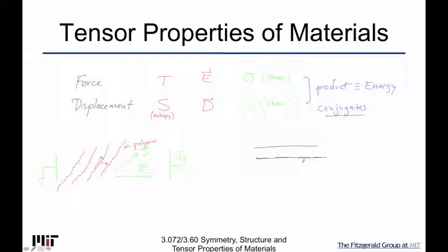But if you keep on growing on a substrate like that, you'll get something that is analogous to polycrystalline, where you have these sheets that have nucleated and they grow on top of each other very well, but they don't grow over here very well. And you might have seen pyrolytic graphite crucibles. You actually can machine this stuff, and it's real material. It's just that it has a particular form because it was seeded always on a substrate, and so you get these regions where it was seeded, they come together. And so it's almost like a single crystal of graphite, except that of course you've got all these regions in between that are kind of messy.